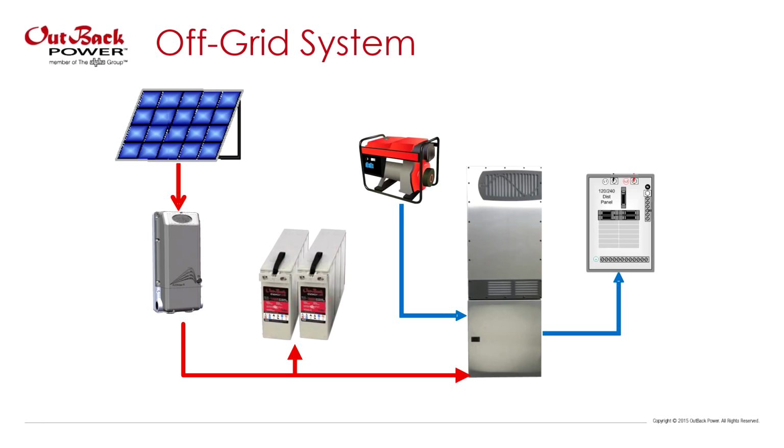So what the charge controller does is it steps down that voltage. So for example, let's say this array is a 300 volt array. So this charge controller would step down that 300 volts to a safe 48 volts. Let's assume this battery pack is 48 volts. And this is just making sure that the batteries can safely be charged. So the charge controller, the batteries, and the inverter all share the same point here, and that's called the DC bus.